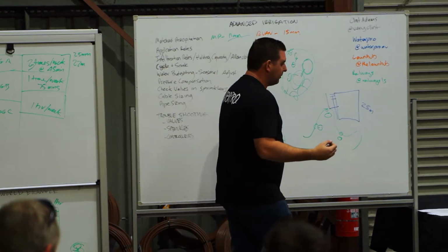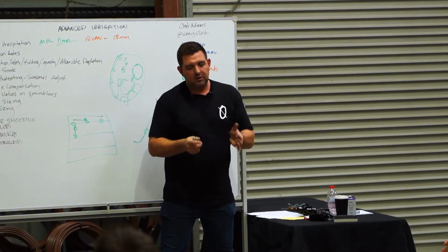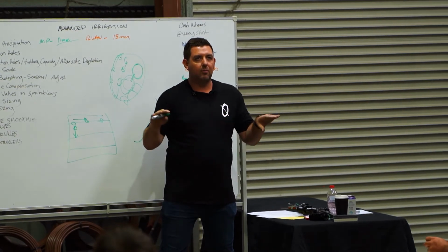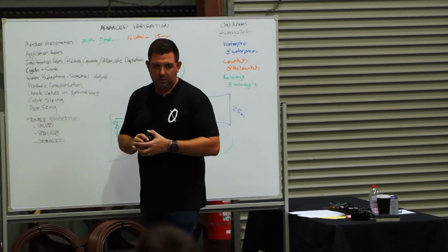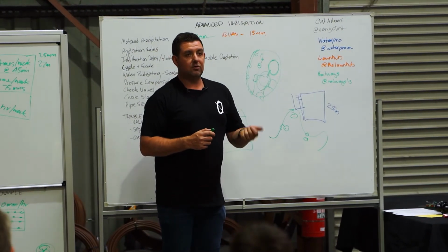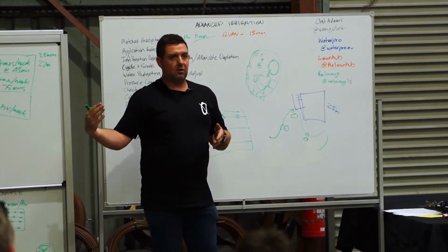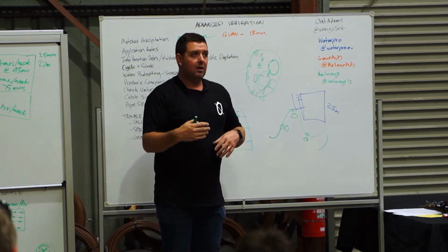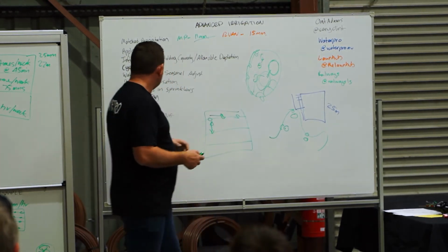So pressure compensation is important to understand. I guess the bottom line is every product that we sell that delivers water that's a professional brand has a predetermined amount of pressure that it works best at. It's your responsibility as an installer to ensure that you do the best you can to deliver that pressure so that the dripper or the sprinkler is throwing what it's meant to throw.